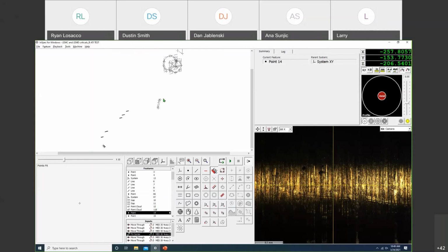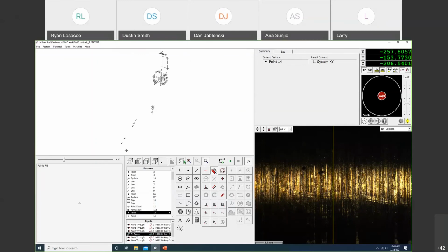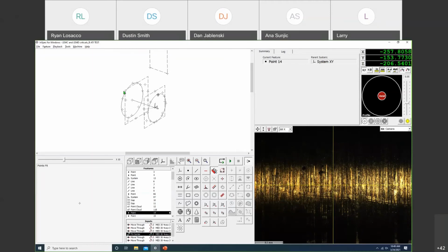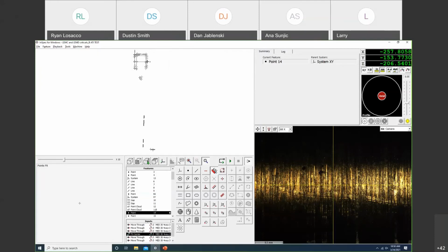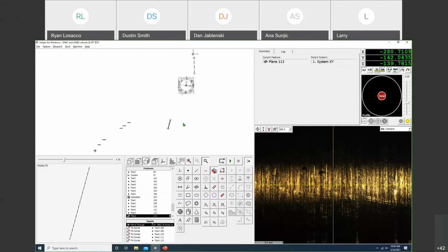So for this feature here, the datum structure was a cylinder through the part, so we got our line there, and some planes that controlled our 6 degrees of freedom. But when we were looking at the blueprint, if I look at the side view here, they needed this plane distance from the origin.